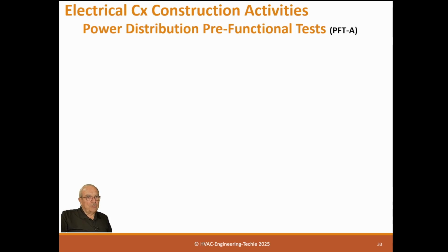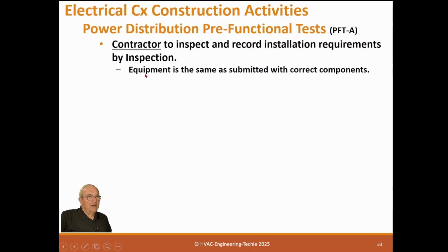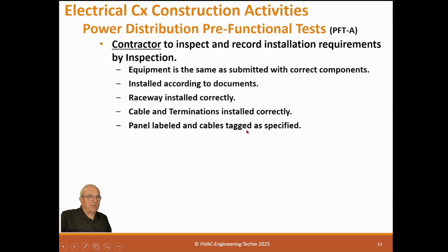Okay, power distribution pre-functional test. Pre-functional test, this is the A test. Contractor to inspect and record installation requirements by inspection. Equipment is the same as submitted with correct components. Installed according to documents. Raceway installed correctly. Cables and terminations installed correctly. Panel labels and cables tagged as specified.